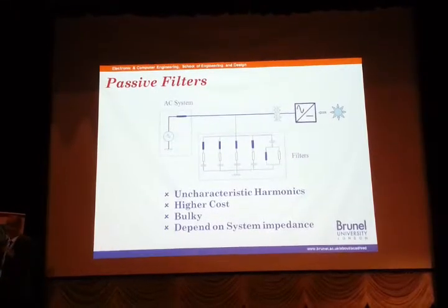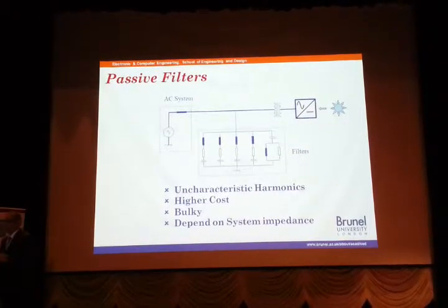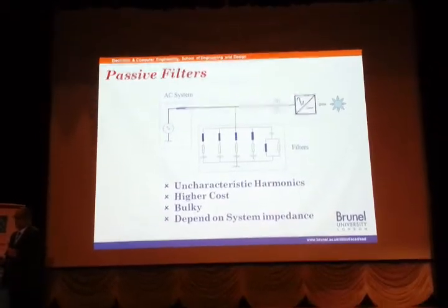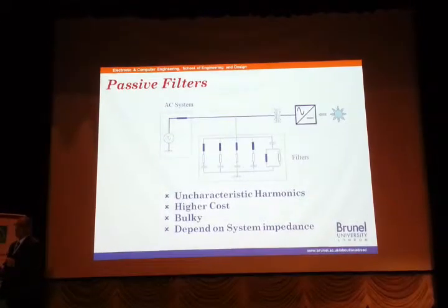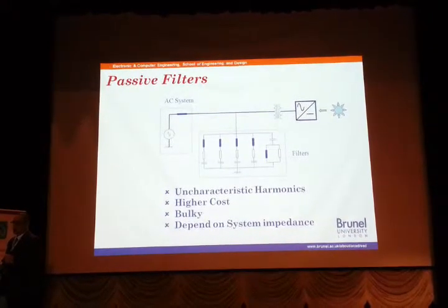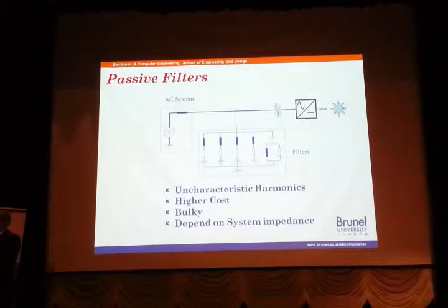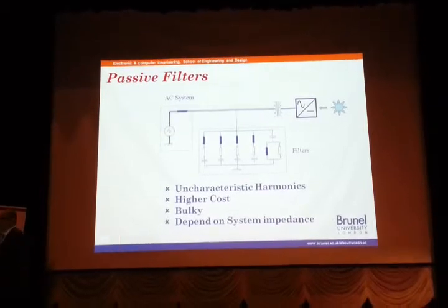It's okay. So my question is, usually you try to probe, let's say, RF power. I used to work at Intel. Usually we want to deliver RF power to the glass machine, and we have a matching network, an automated, very sophisticated algorithm, because the plasma impedance is varying all the time. So we keep tuning the power all the time with a sophisticated algorithm to have complete matching. So try doing the same thing for the harmonics, so that you have an adaptive system where you build a complex algorithm that will match.